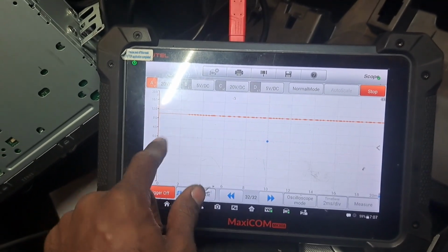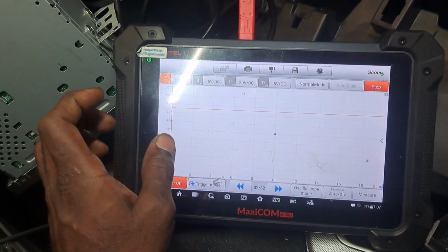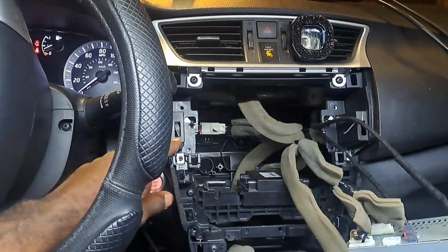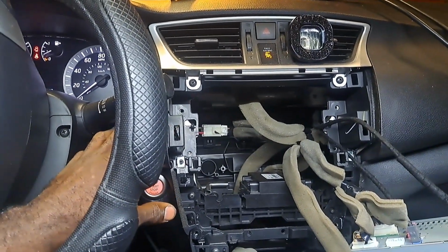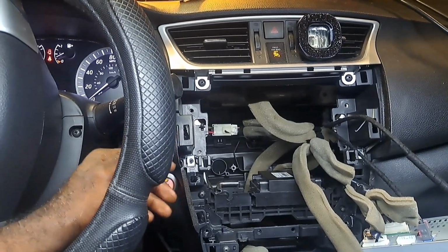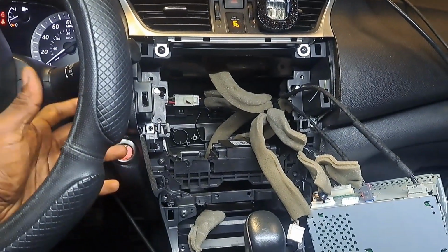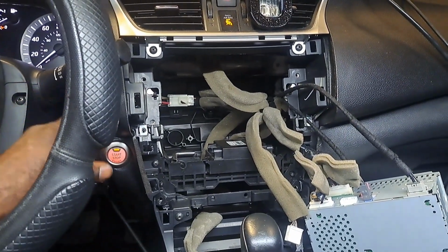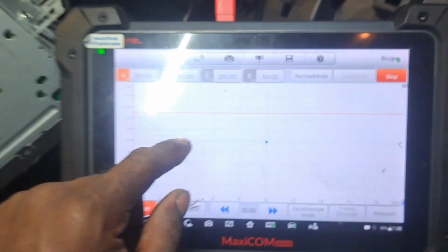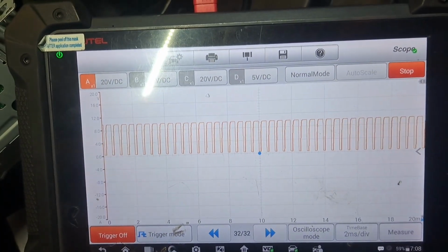So right now, this should be backfed voltage from the blower resistor, because it has power and ground. Now that's probably likely due to it being just a reference circuit, like bias voltage, to ensure there's some continuity. And if there's some issue, it's going to detect, like, hey, there's some circuit fault, I'm assuming. But this is our reference voltage here. So being that I have this disconnected, let me plug this back in. Let's see what happens. Yeah, it shows that again.